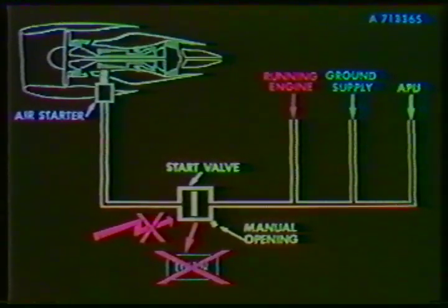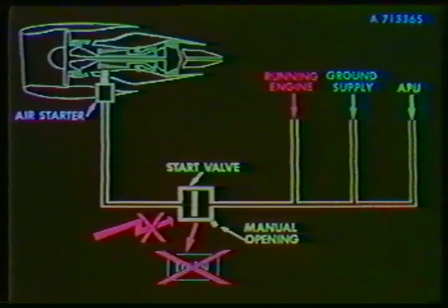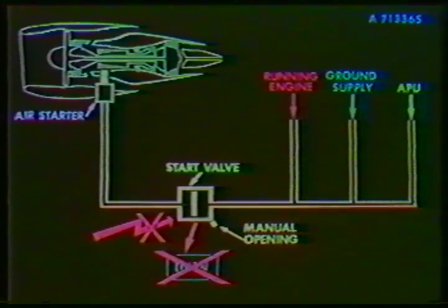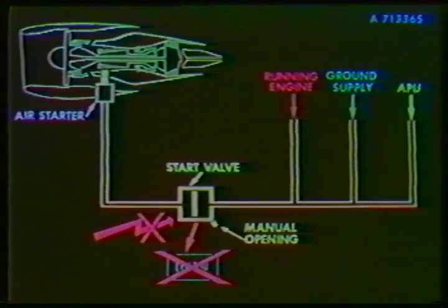If the start valve remains closed during start due to an electrical failure, the open light does not illuminate and engine start is not possible through this method. But the start valve can be manually opened on the ground through a door on the engine nacelle.